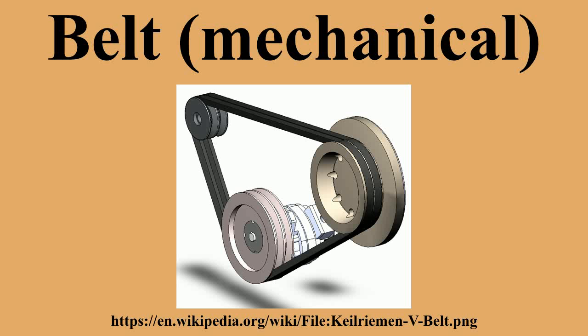Belt vibration. Vibration signatures are widely used for studying belt drive malfunctions. Some of the common malfunctions or faults include the effects of belt tension, speed, sheave eccentricity, and misalignment conditions. The effect of sheave eccentricity on vibration signatures of the belt drive is quite significant. Although vibration magnitude is not necessarily increased by this, it will create strong amplitude modulation.